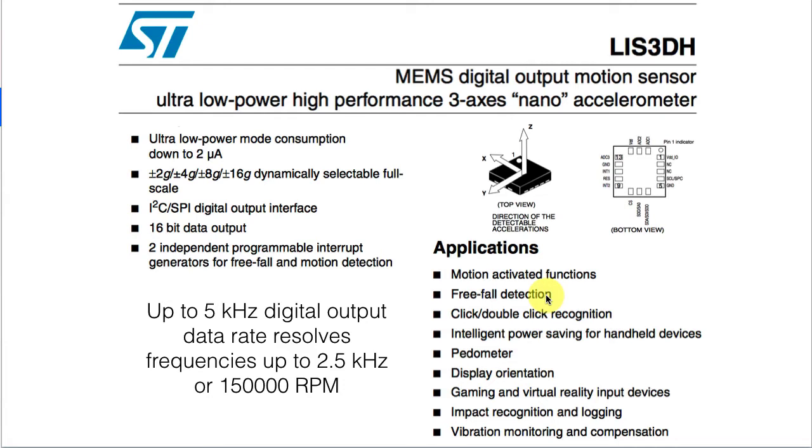If we're continuously detecting gravity and suddenly we detect no gravity, we've got an immediate indication we're in free fall. And whatever this device is, we'd better do whatever we can to protect it before it hits the ground. If it's a hard drive in a laptop computer, we could at least park the hard drive heads before it hit the ground. And that would be a considerable advantage.